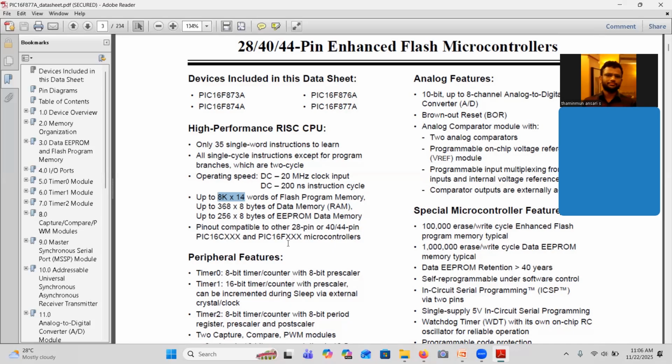Yeah, almost. We will have different peripherals and they are interlinked with the memory. But peripheral is not a memory. Yes, they use memory. Peripheral is a logic circuitry, to communicate with the external world. Within a microcontroller, it is a digital logic for timer, digital logic for analog to digital conversion.